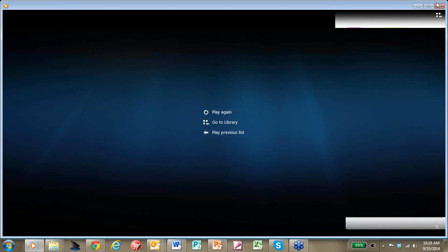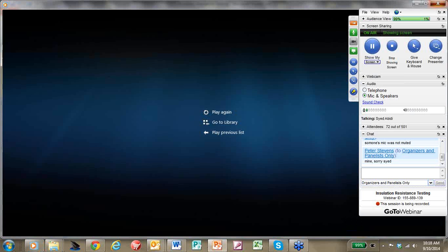So we're going to continue with our presentation here. Most insulation resistance testers have a variable output voltage. The test voltage is usually specified at 500 volts or 1,000 volts by the safety standards. Now this requirement may change if the insulation resistance test is an internal company requirement. The voltage may change here, but going by the standards, this is what is normally called out for, 500 volts to 1,000 volts.